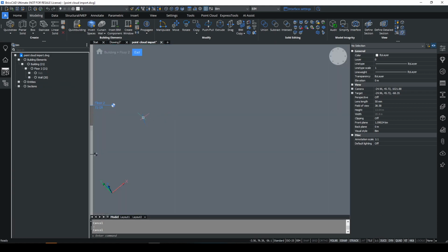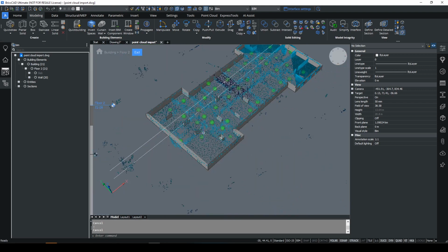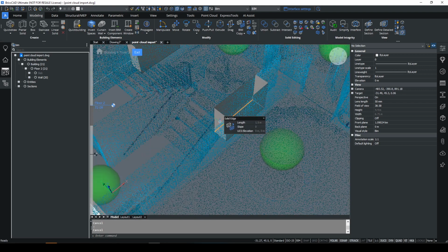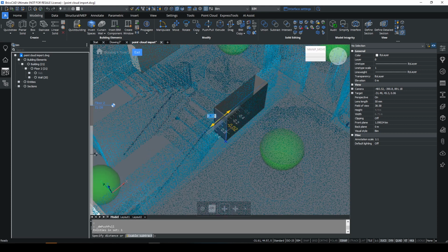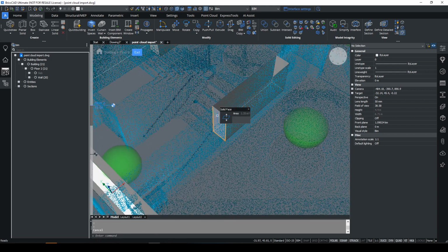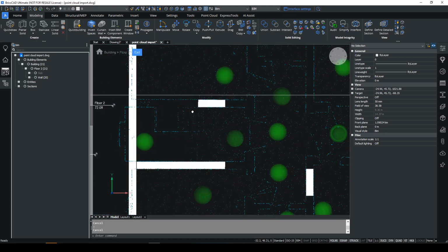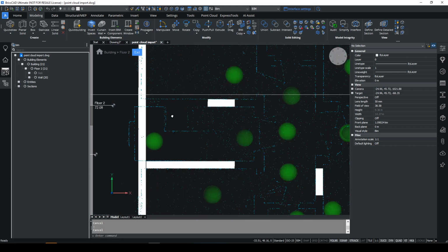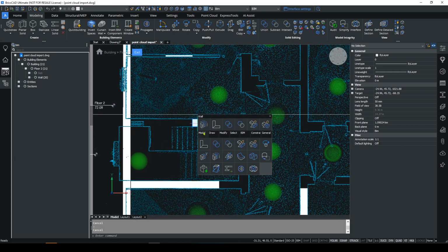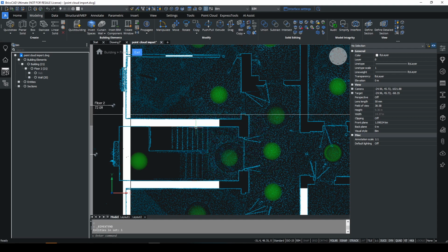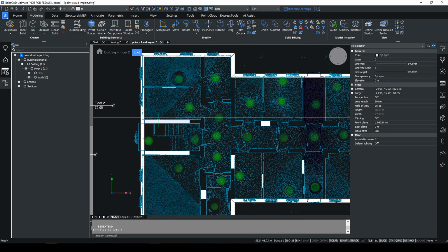Previously, what we would do here is go to a 3D view and click on the area of interest, and you could either use the push-pull command, or you could use the connect with nearest wall command on the face. That works quite well, but everybody wants to work in plan views these days. So the way we have fixed this in V23.2 is we've got new commands called BIM trim, BIM extend, and BIM slice, and these do exactly what you'd expect. So you can go to BIM extend, hit that wall, and extend it to meet the external wall.